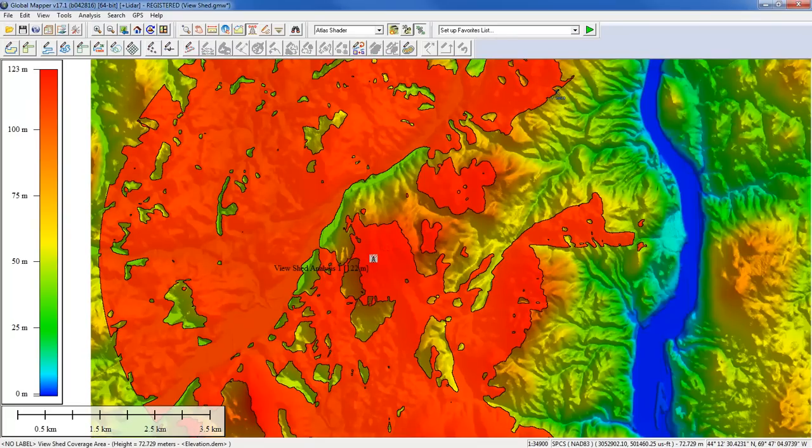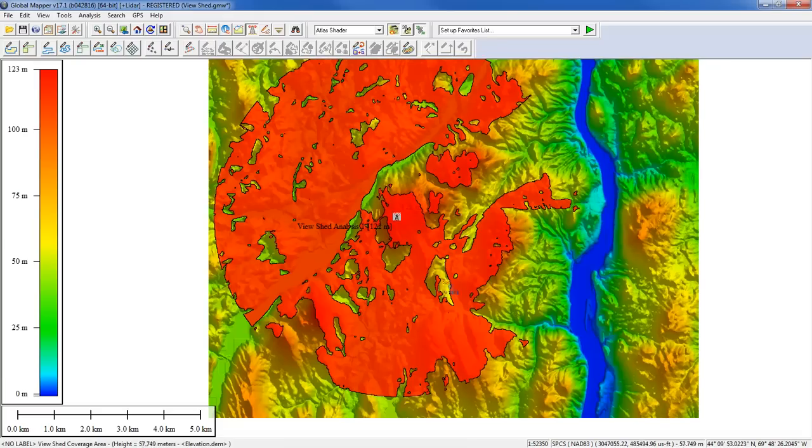And one of the options that I did not show you, perhaps it would have been more useful in this context, is not to map what I can see, which is what I have here. I basically have the red areas indicating what is quite literally visible from this point, what can be seen. If I was hoping to hide, I could certainly occupy some location in here, and I could not be seen from the top of that 10-meter tower that we've defined. So red equals covered area. The area that's not shaded represents areas that have no coverage, that are in shadow.